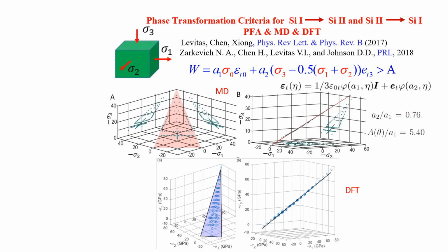That is why we develop four-scale approaches. At atomistic scale, our goal is to find a phase transformation criterion, not phase equilibrium, but phase transformation criterion, on the action of all 6 components of stress tensor. Due to the large number of combinations, this seems to be impossible, but we are also working at continuum scale.